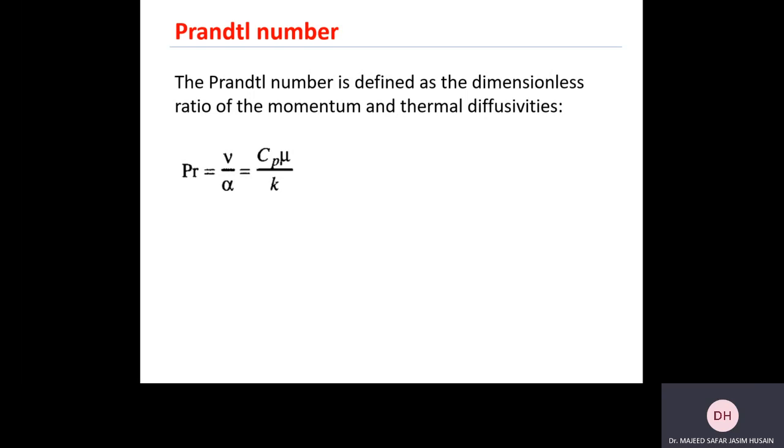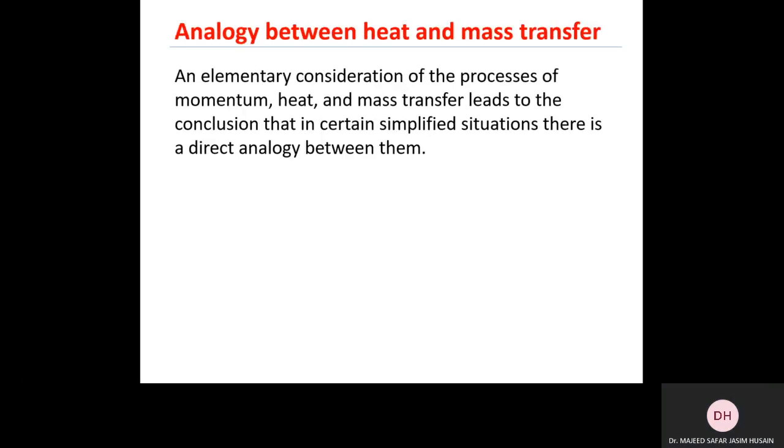An example of this kind of operation is the humidification operation. You have probably taken this in thermodynamics. You have the water vapor, which will be humidified. There is a kind of mass transfer because there is evaporation, and you also have condensation happening. So there is mass transfer, and there is also a change in temperature, so there is heat transfer. It is combined nicely in the Lewis number.